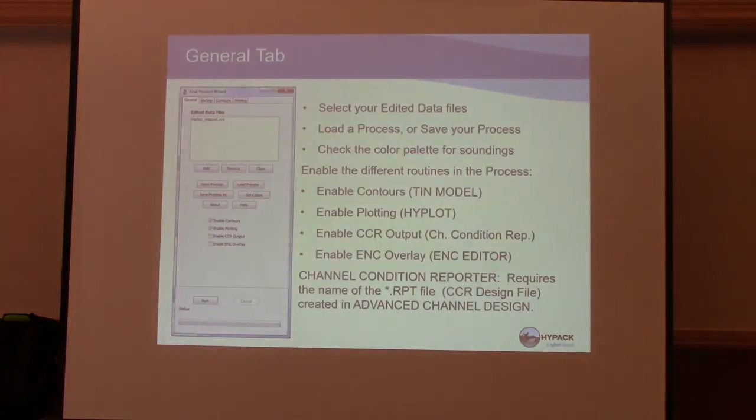So this is what the program looks like. I'll run through a couple of the presentations here, and then I'll run through the program. When this pops up, you'll have a bunch of tabs right up at the top of the screen. The first thing you do is add your edited data files. This could be XYZ data, logs, multi-beam data, and pretty much any of the sounding data that you want to load into the program.